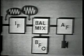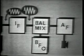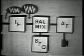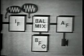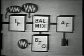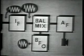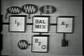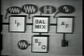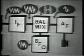So if we insert an RF oscillator, let's call it a beat frequency oscillator, or BFO, to generate a constant frequency 1 kilohertz below the IF signal, like the original carrier, and mix it with the IF, the result is, of course, 4 frequencies: the IF, the BFO signal, an upper and lower sideband, or a constant carrier with sidebands of the audio difference. The resulting phase relationships restore the original envelope variations, and we can easily detect our audio.